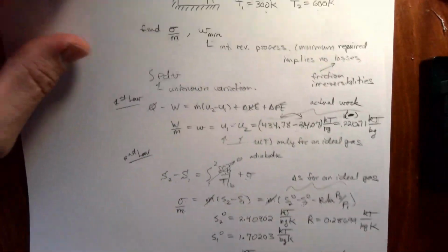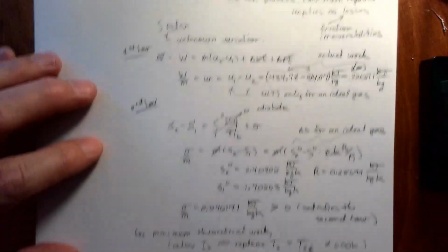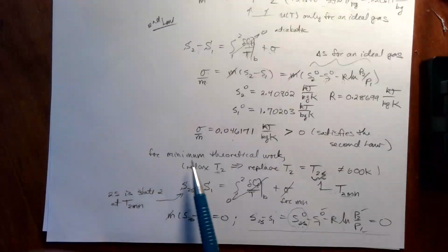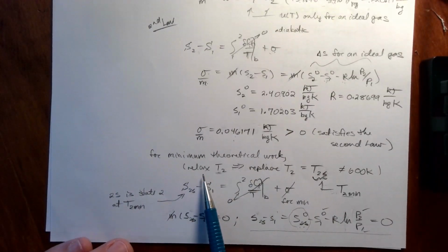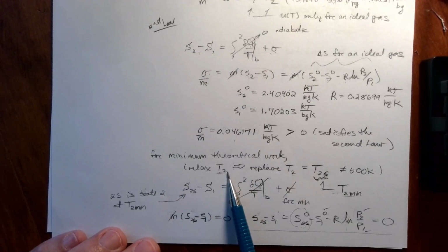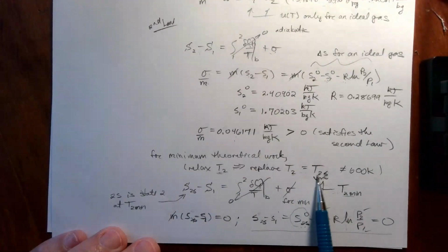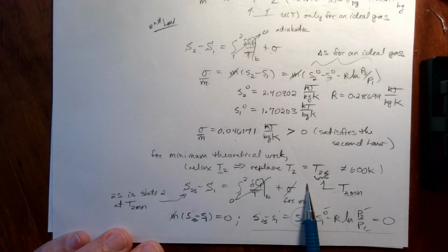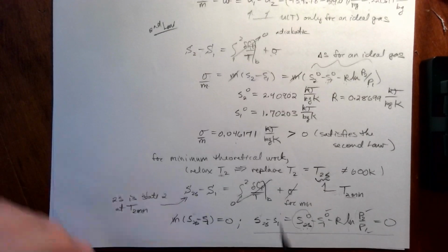So for this problem 43, the interesting discussion here, if you're going to make comments about this problem, is this part when it says to come up with the minimum work. We have to know that it's the temperature that we're going to relax so that we can apply a restriction that it be internally reversible and so isentropic. And then we calculate a new T2 and then a new amount of work for the reversible case.